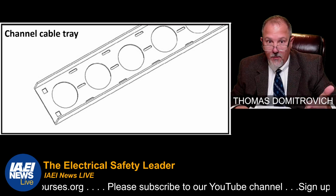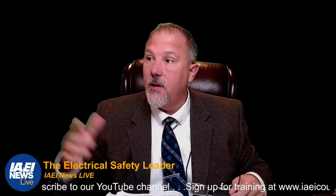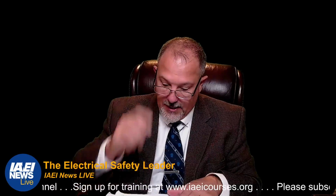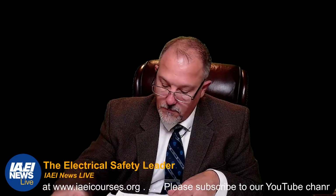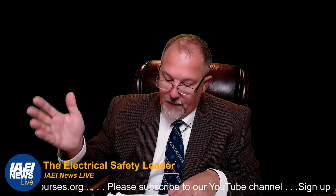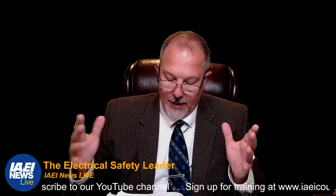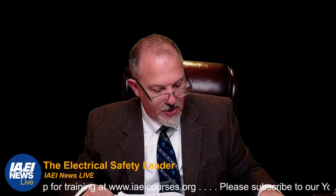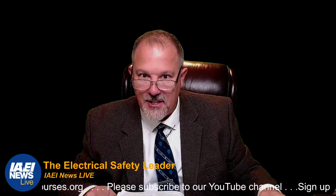Now they do have one definition, and I can tell you that the definitions in the 2023 code cycle are all moving to Article 100. So that's a given. This definition for cable tray system is an assembly of units or sections, and all of the fittings forming a structural system used to securely fasten or support cables and raceway. So they define a cable tray system. Now I wonder where in here they use that term. They do. Cable tray installation. They've got a complete system in section 392.18.